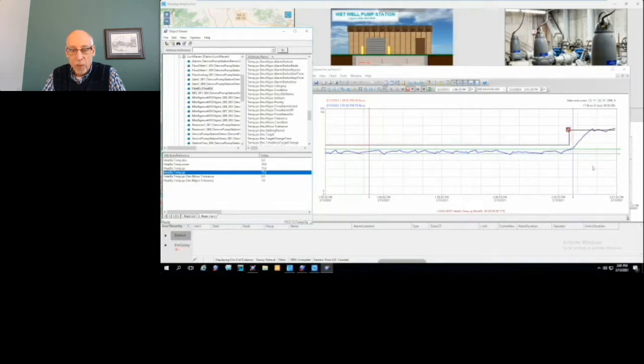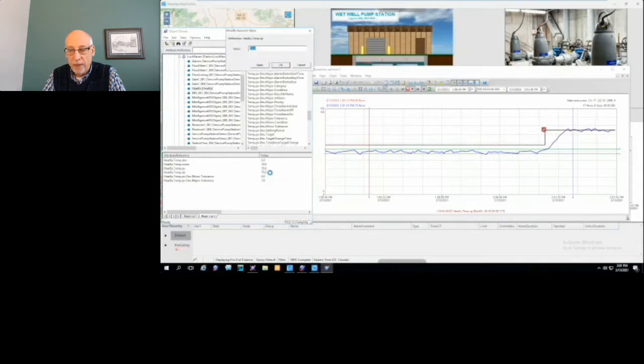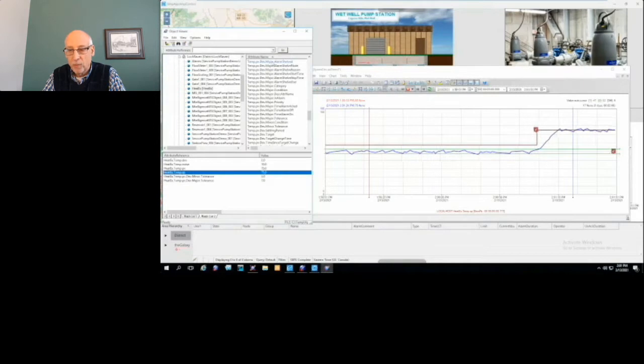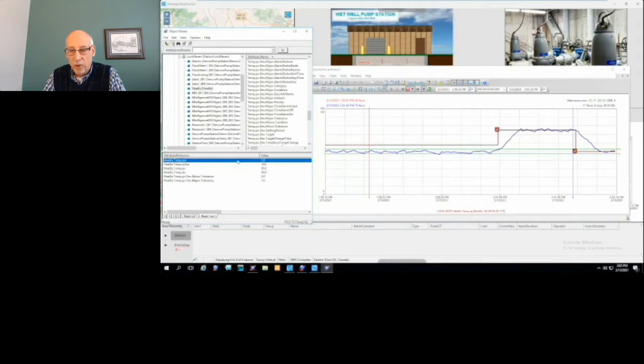So I'm going to put it back to where it was, so it centers it on my screen, and then we'll introduce some more noise, and we'll give it more deviation to generate the actual alarm. So you can see it skewing back into control. We'll let it settle down there a little bit, and then we'll introduce some more noise to the system and generate a deviation alarm. So I'm going to change that deviation set point there in my simulator, so it's going to generate an alarm because it's going to skew out of control from that actual set point, and introduce a little more noise here.